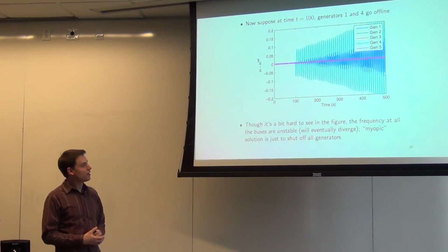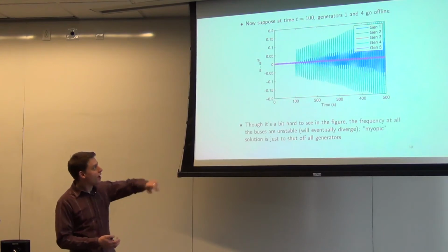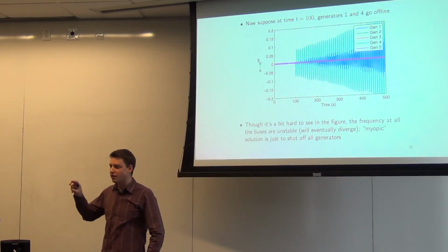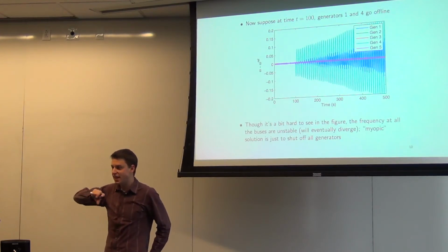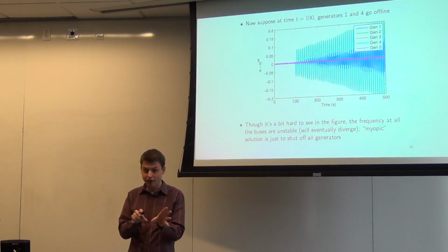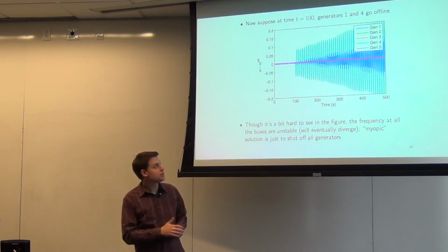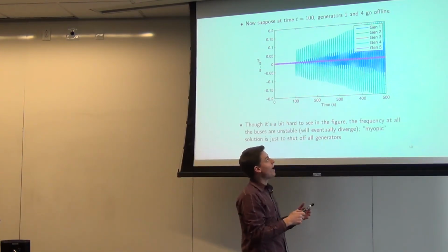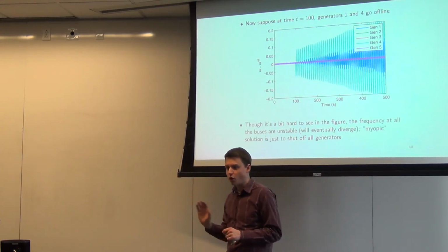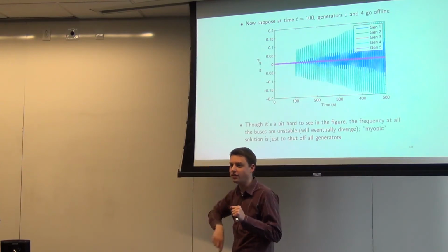And now something really sort of bad happens. As you can see, their effective angles... every node has a power angle, regardless of whether it's an actual generator or not. Loads all have a power angle at that load too, so we can track their angles even if they're not a real generator. What happens here is that when they go out, as you can imagine, the other generators in the system don't really know what to do from this, and so their frequencies at the generators start oscillating.